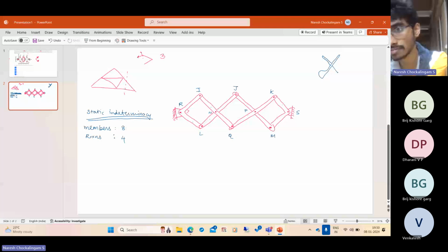If you draw the free body diagram of both, right? This is one arm, this is the other arm of the scissor. You need to put the reactions 1, 2, 3, 4, and you have the pin force, equal and opposite pin force. So there are two components of force coming from the pin connection. So there are unknown forces which are holding these two together.